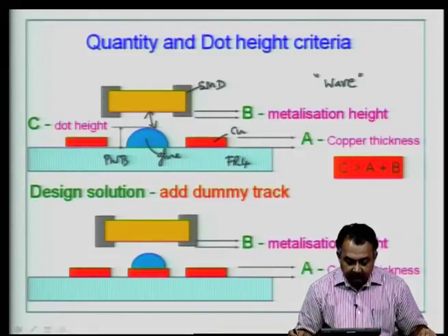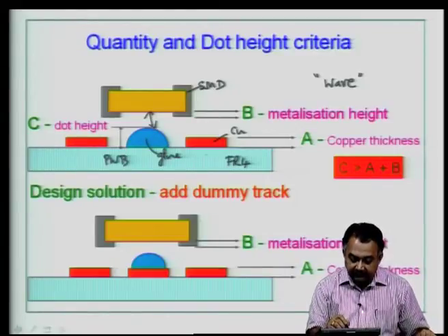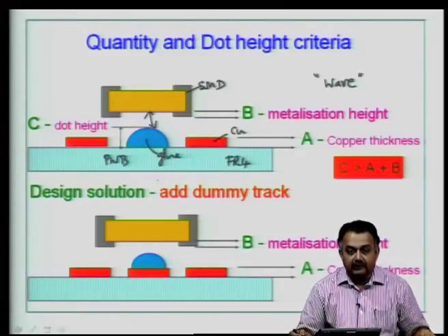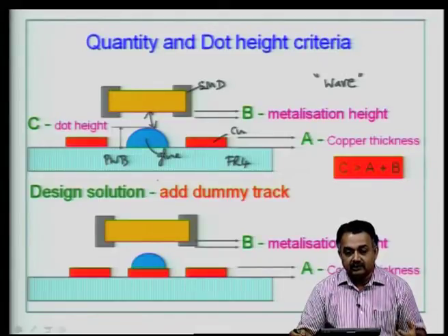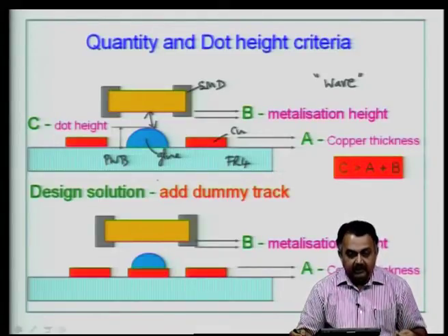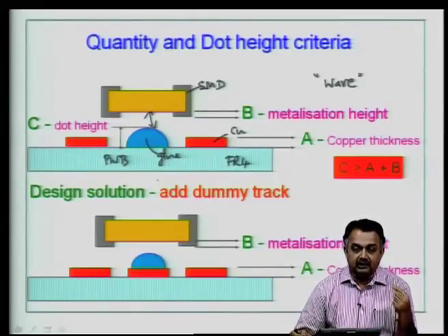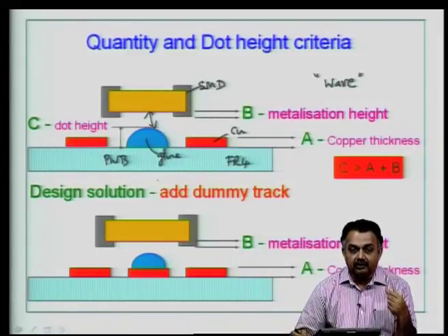Now, in some cases what happens is that because the pad height, the thickness of copper, is very low, you are dispensing too much glue, and for a small device, dispensing too much glue economically cannot be possible in large companies, in large volume production. So, the idea in some companies is that during the design stage itself you take care of minimizing the quantity of glue.